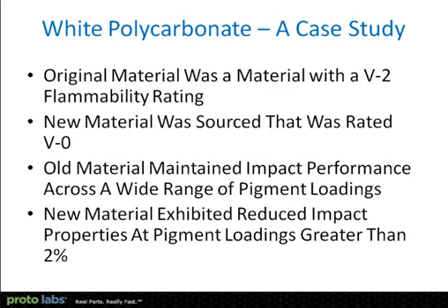And the way we ran into this is we got a batch of resin in from the compounder. These were fully compounded material, so there's no color concentrate being used. Everything's coming in, it's all white. And we started to mold the material, and we started noticing notch sensitivity in a particular part. And when we did the pigment analysis, we found we had nearly 4% pigment in the bad batch. We looked at a good batch, and we had 2%.